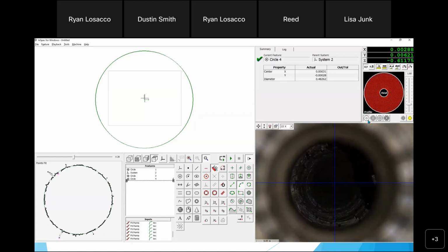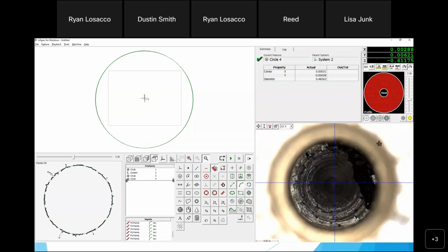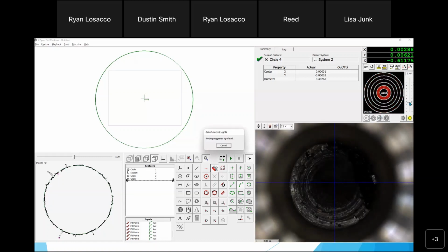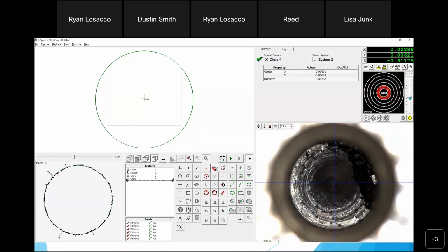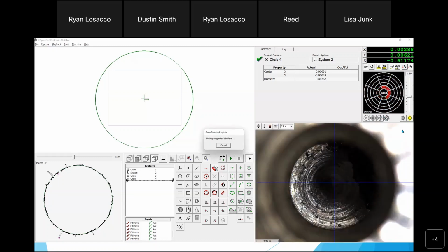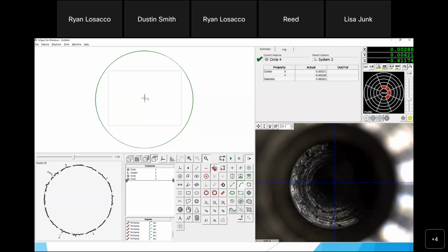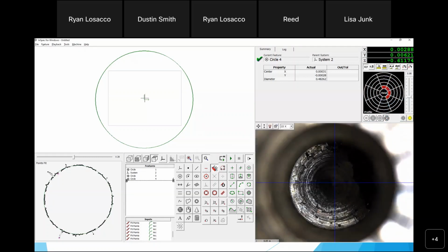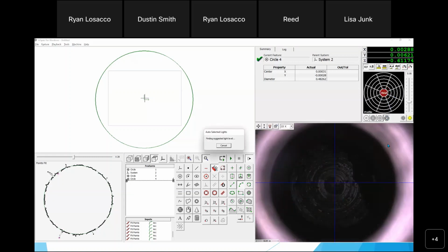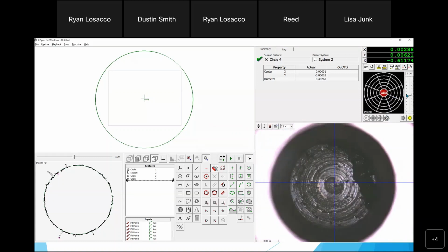Let's look at the difference between full surface light and ring light. So I'm just going to use a center ring light. I'm going to bump my lights up a little bit. Pretty much the same. We could also, if we know we're casting a lot of shadow over here, maybe we could have lights just coming from this direction. So all I did was switch the segments, my inner ring light just from that direction so I can get a crisper edge going on right here. Sometimes axial light helps, but it might get cloudy. See how cloudy